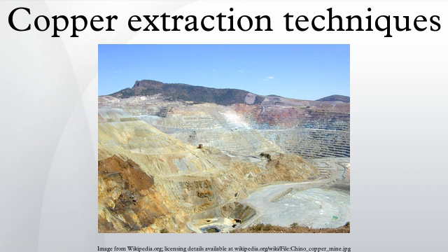Most of the reverberatory furnaces used in the latter years treated roasted concentrate, because putting dry feed materials into the reverberatory furnace is more energy efficient, and because the elimination of some of the sulfur in the roaster results in higher matte grades. The reverberatory furnace feed is added to the furnace through feed holes along the sides of the furnace. Additional silica is normally added to help form the slag.